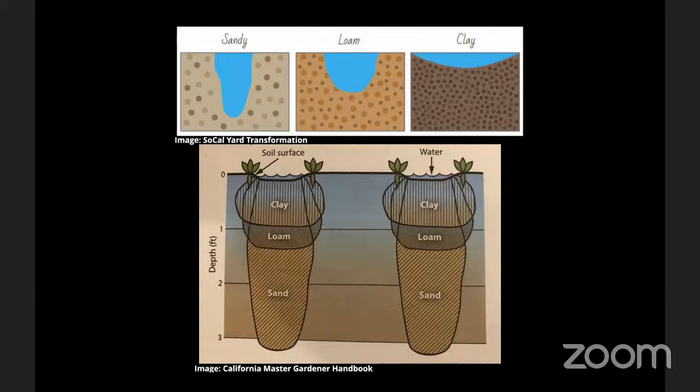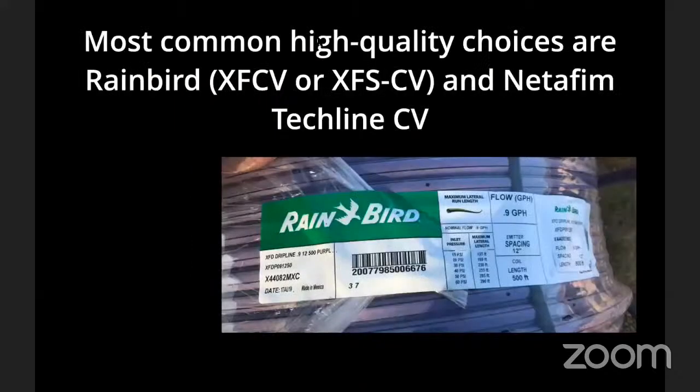Generally, it's going to be after the valve. You're not going to want to have it before the valve, because before the valve, the system's always pressured. It needs to be after the valve, which means you're limited to one valve for that installation, or having to uninstall and reinstall it. That can be kind of a pain if you have a really varied backyard. And then the question about spacing on the slope, I have a slide for that later on. So just hang on with that.